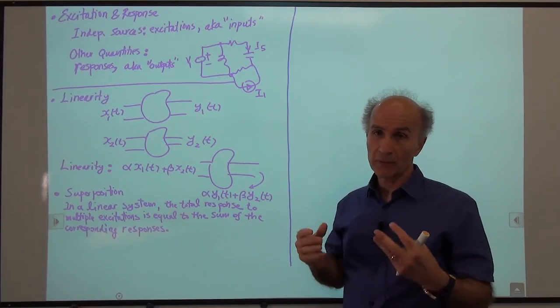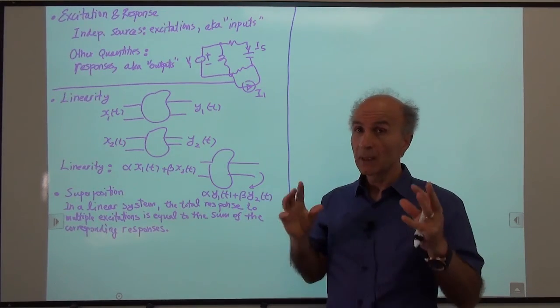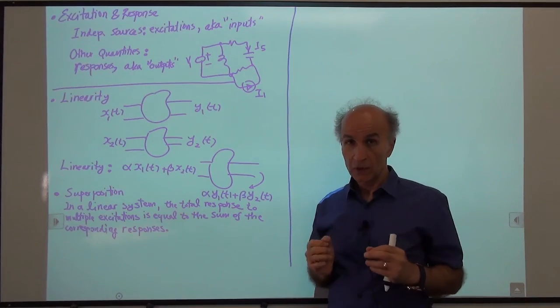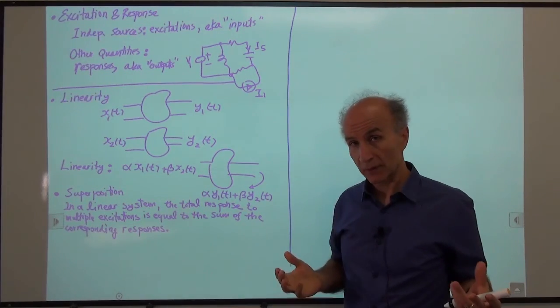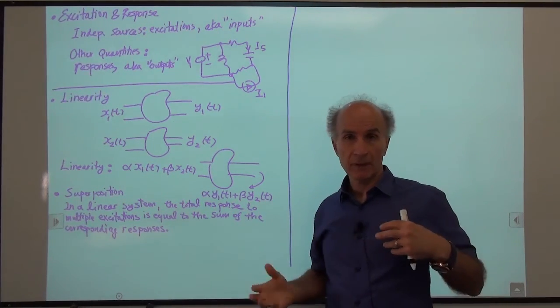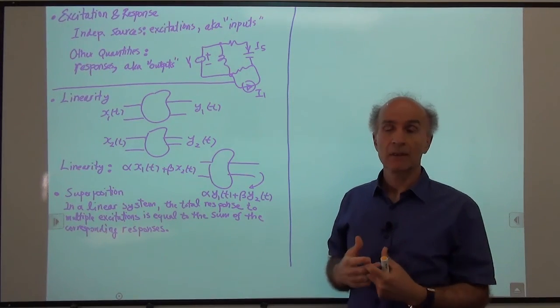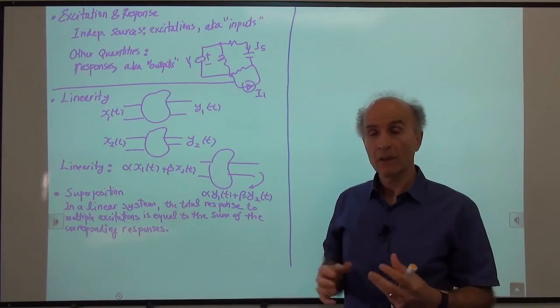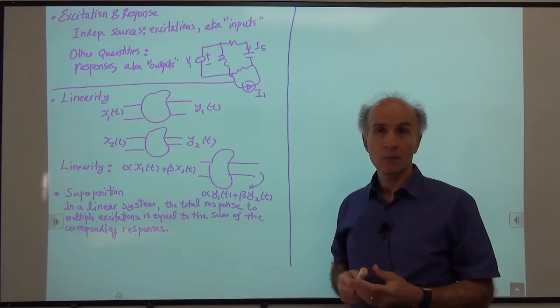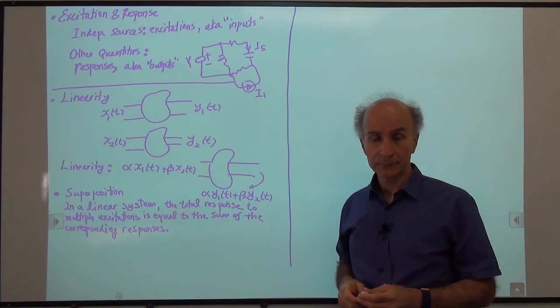So anytime you have a circuit with multiple inputs or excitations, you can immediately consider superposition, right? Whether it's faster than our previous types of analyses, node analysis, mesh analysis, etc., maybe not. It just depends on what we're trying to do. But in some cases, superposition is extremely helpful.